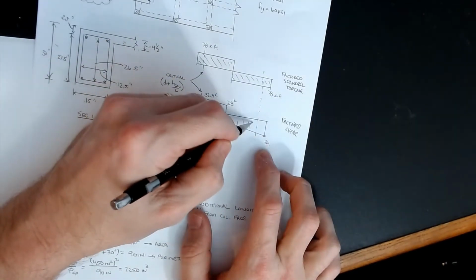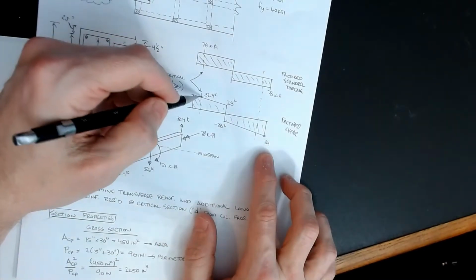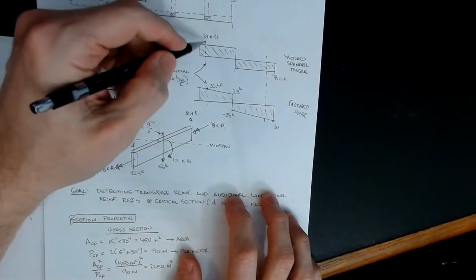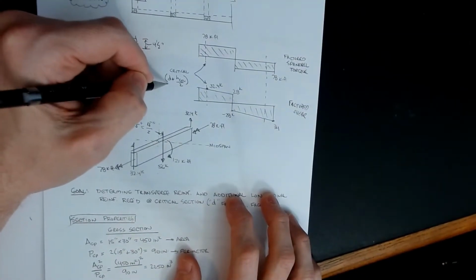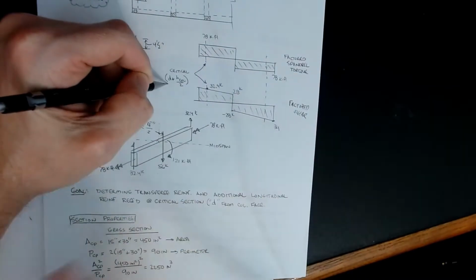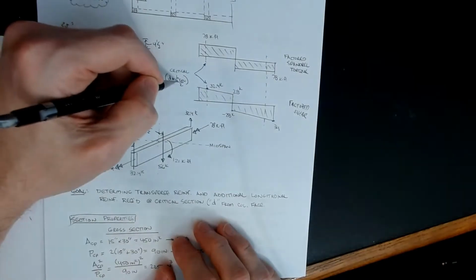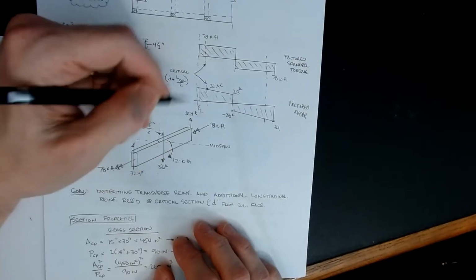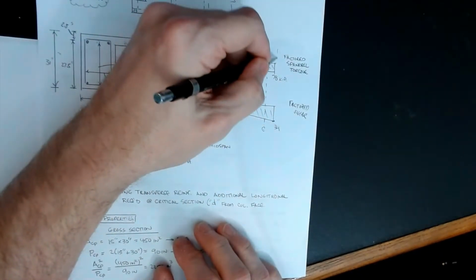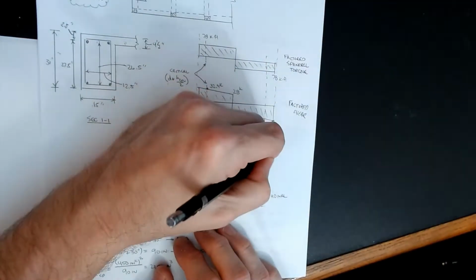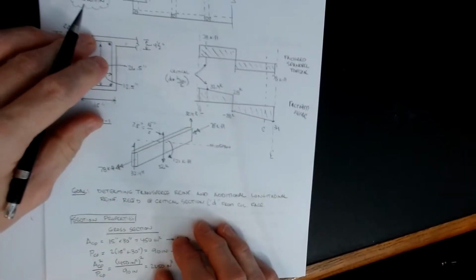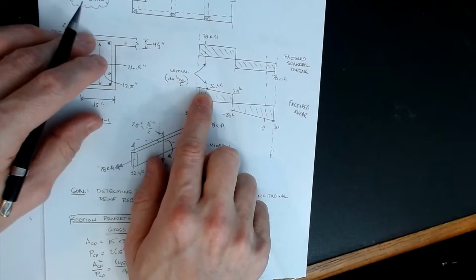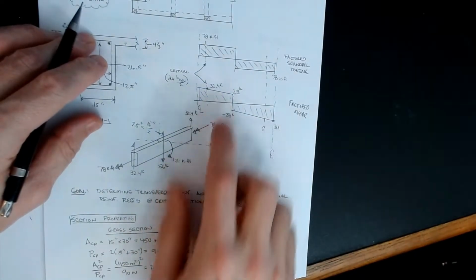Now, again, if you remember from shear, we don't design for the maximum, we design for the shear at a critical location. Our critical locations are these dotted lines, located at a distance of d of the beam, which remember was always d from the face of the support, plus h column over 2, because these are all center line column dimensions. The one that's here is the center line dimension as well. So if I find the critical value, we're coming in that distance from the center of the column to get to d from the face of the support. So that's 32.4 kips on that.